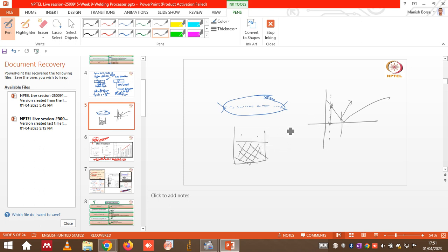So there won't be sufficient liquid, or a continuous film of liquid can also form. So those alloys undergo solidification cracking compared to any eutectic composition. So I hope it is clear.